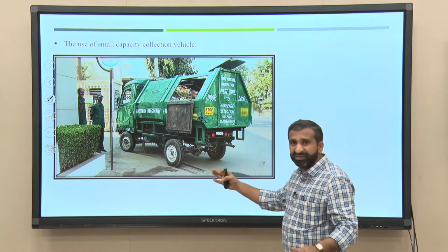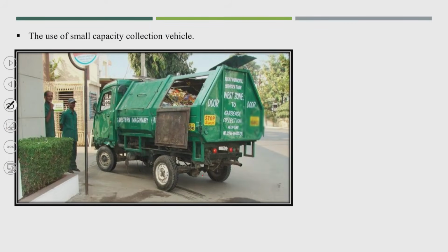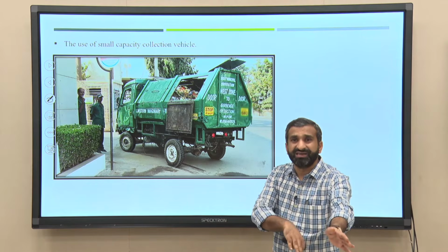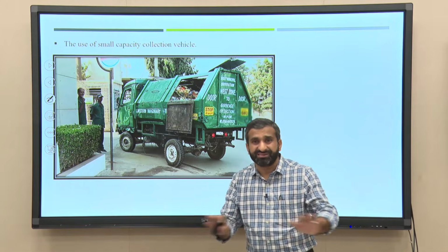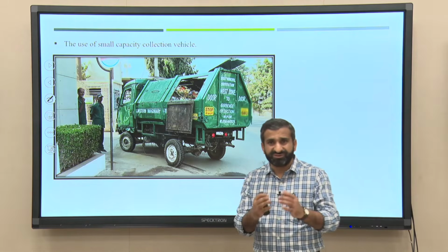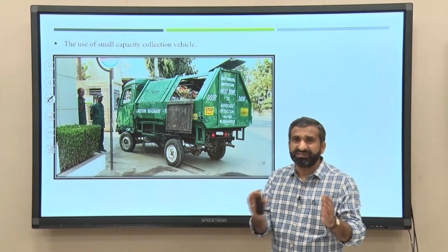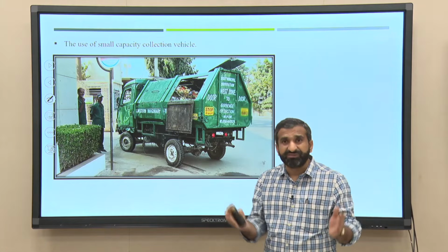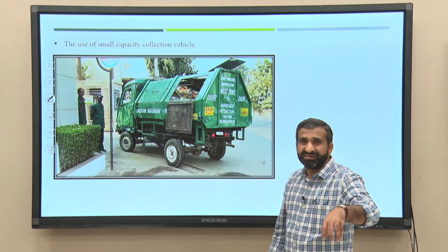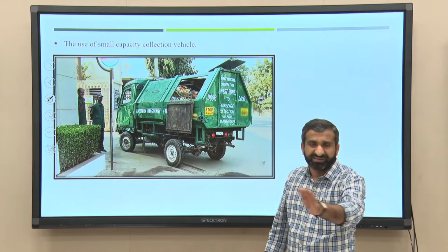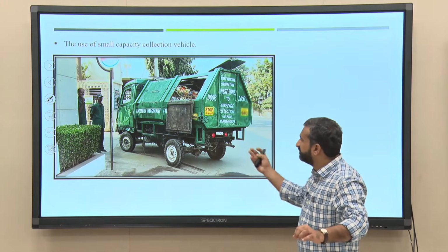So, why not, if there are transfer stations very close, we can have smaller vehicles, and these smaller vehicles can go directly to the transfer station, without needing to go to the storage area or dustbin area. So, because of the transfer station you can avoid dustbins in the city. In one of the lectures I shared whether it is possible to have small cities without dustbins, or dustbin-free cities. Yes, it is possible if you plan transfer stations very close to the residential area, but there are some issues which I will discuss in the further slides.